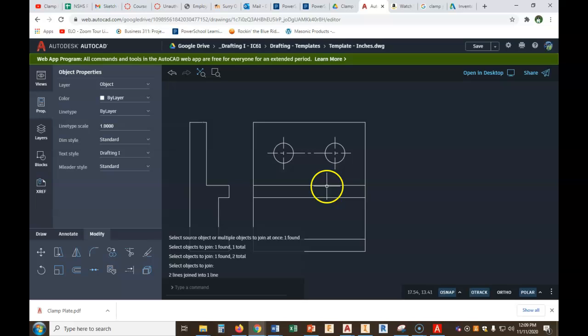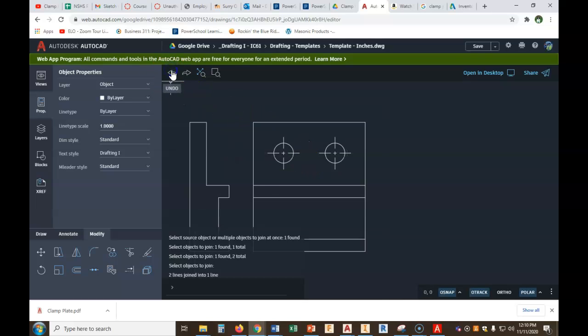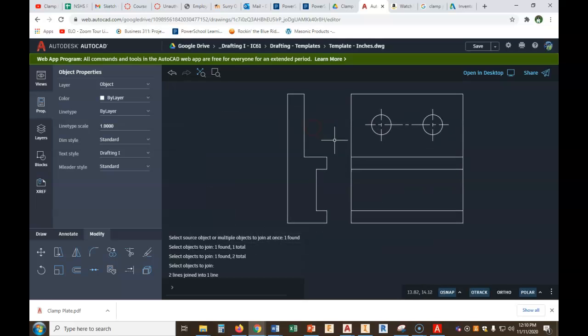Okay? There we go. Yes, I know it threw our little crosshairs off. If that really, really, really troubles you, then don't do it. Leave them like that. Okay? But AutoCAD does that because what it does is it spaces out the little short dashes from end to end. It doesn't take into account that they're in the center of a circle. Okay? It does this way because it's exactly the same distance here and here. So there we go. Now, here's the thing though. Remember, we've drawn all our visible edges and our center lines, but here's what we haven't drawn.